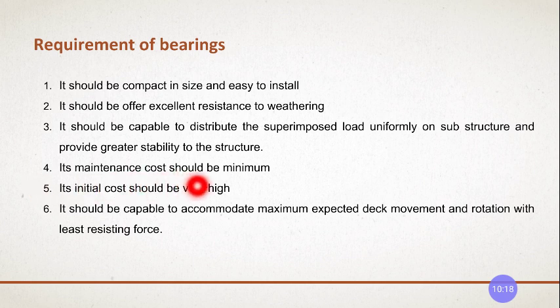Its maintenance cost should be minimum. Its initial cost is very high. This is one of the problems in the bearings. It should be able to accommodate maximum expected deck movements and rotations with least resisting force. It should be able to withstand the rotations and longitudinal movements of the bridges.